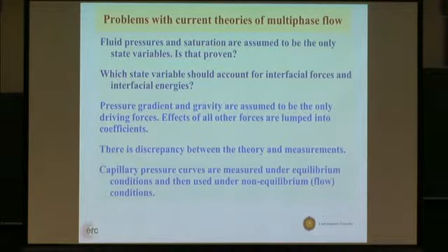So the fluid pressure and saturation are not the only state variables. There must be something that accounts for the fact that these menisci are there. There is interfacial energy playing a role. And pressure gradient and gravity are not the only driving forces. Imagine for single phase flow, these are the only ones, but when you go to more fluid phases present, there are other effects, the capillarity effect, that should appear in the equations.